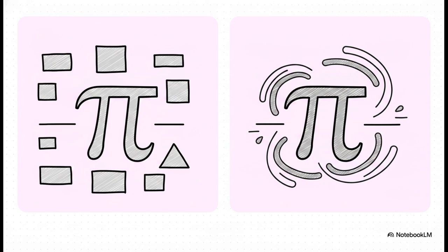This comparison brilliantly illustrates the core difference between the two approaches. Nominal pi is our lumped parameter workhorse, perfect for those medium routes where we can just split the capacitance and call it a day. The equivalent pi model, on the other hand, mathematically corrects for true wave behavior. Structurally, it looks completely identical on a diagram, sure, but the actual component values have been heavily modified by those hyperbolic functions to account for the reality that voltage is traveling as a wave over hundreds of kilometers.